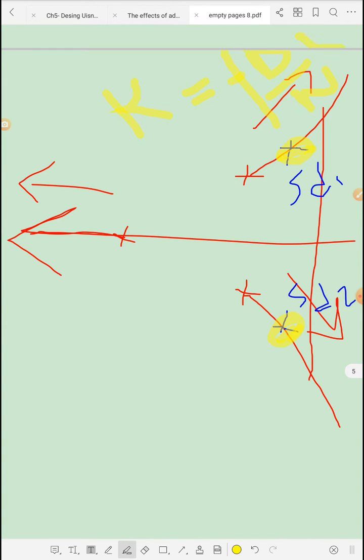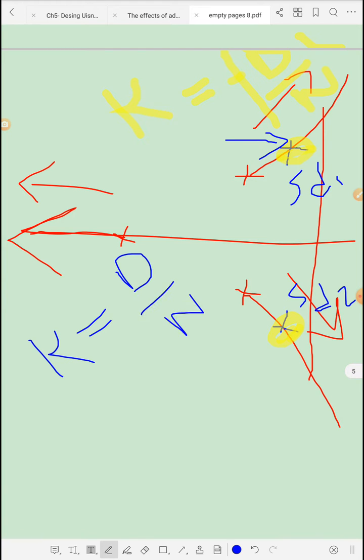There is no need for the minus, we take the absolute value, and based on this step we calculate K. K will be the magnitude of D over N of the original plant, without any addition of the controller, at SD, the desired location. Its value will be from 0 to infinity, within our range, because it lies on the root locus.